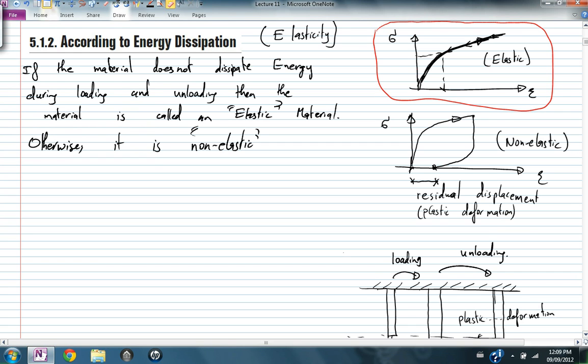So basically, the stress-strain curve of traditional materials, a linear elastic material, is just a linear line between the stress and the strain within the range of applicability of the material. Materials like rubber or other polymers, you might find that the relationship between the stress and the strain is non-linear but still elastic.